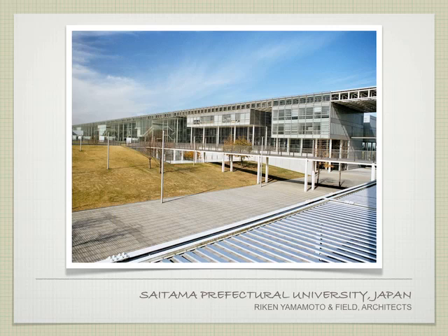And so they had to open the university, they had to get the buildings done, and they didn't have enough time to do it. So they switched methods, and they said, you know what? We're going to use as much prefabricated concrete elements as we can. There'll still be a little bit of site cast, but we'll switch to the prefabricated elements because all of those can be made in bulk off-site, and it dramatically decreases the time for us to build it on-site. We only have that half, 3/4 of a year left, 9 months left to build this. If you can prefabricate all these elements, we don't have to wait for our concrete to cure before we can move on, so it can go up much, much faster, which is what ended up happening here.